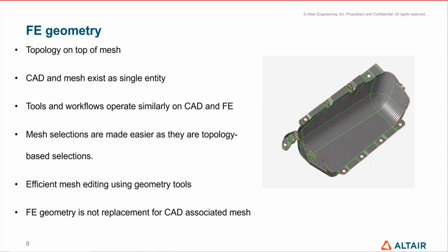Last but not the least, I would like to remind you: FE geometry is not a replacement for any CAD associated mesh. If you have CAD and you're meshing on top of CAD, I suggest to proceed with that and not convert everything into an FE geometry at this point. FE geometry has to be used where you have a mesh and you don't have CAD for it.